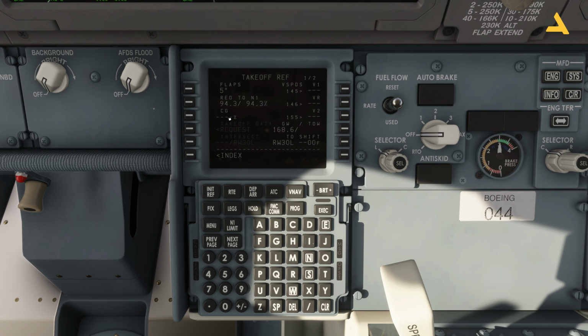Now the center of gravity. Just go back and you will see in the performance that the center of gravity is 6. So just go over here and enter 6. This will give you the settings for the trim, for the elevator, whether to pitch up or down during the takeoff. It's basically nose pitched up by 8.5 degrees during the takeoff. I will just show you right now.